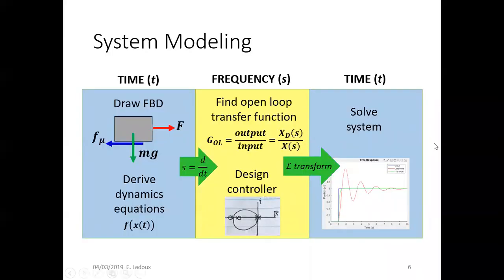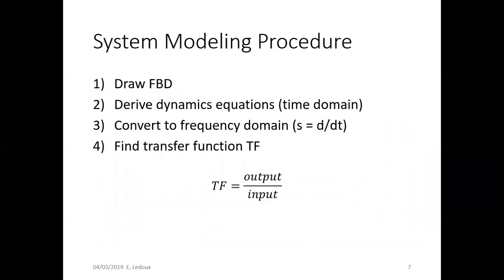So two parts to the system modeling problems. One is the actual modeling, and that is the stuff getting equations in the time domain and converting to frequency domain. That's what we'll talk about first. Then second is the controller design. How do you choose what the transfer function for the controller should be before you can solve the system? So modeling the plant, designing the controller.